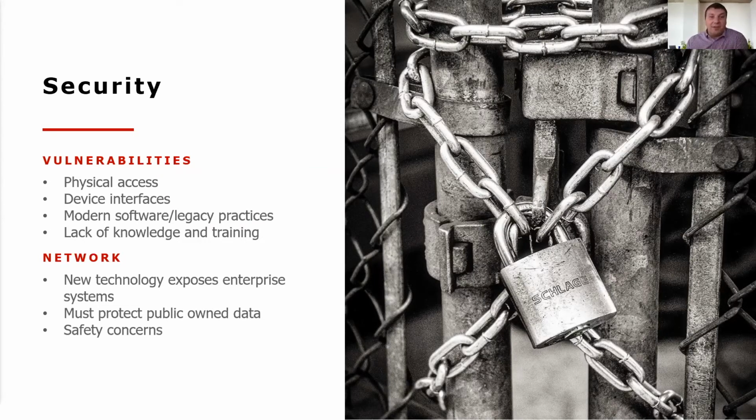Once they're in there, the controllers and other devices don't necessarily have up-to-date security protocols, right? Most controllers until a few years ago only had a 4-digit code in them. And that 4-digit code was the same for everybody. It was a single 4-digit code that restricted read-write access. So you can only imagine if an agency's 4-digit code gets out, it doesn't matter anymore, right? So most people didn't even implement them. And a lack of knowledge and training.